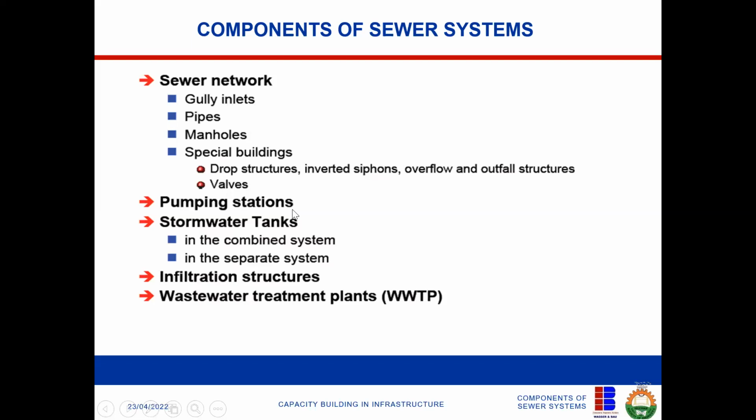Pumping stations are only found at the inlets of the wastewater treatment plants. Why is it so? Because sewage will flow by gravity. And when sewage is flowing by gravity, it means that there will be a head difference between the residential area and the treatment plant.